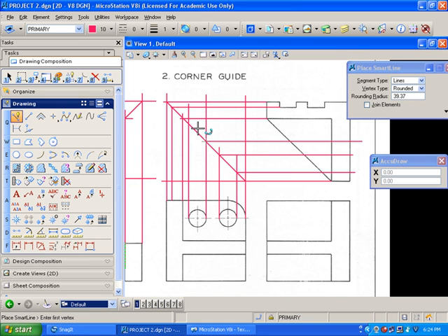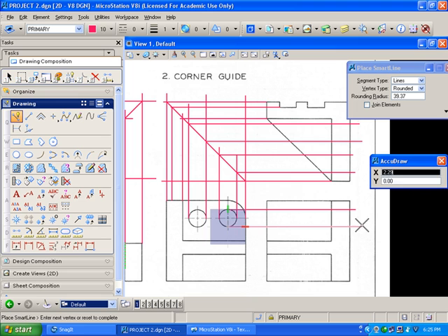Now in this view, the corner view, we're looking at a top view, a front view, and a left side. So it's actually top, flipped up in the front here, and then left side here. We're going to extend these lines over because they line up. We can extend the center line over here and extend the center line up here. Spacebar I, bring it across, spacebar I.